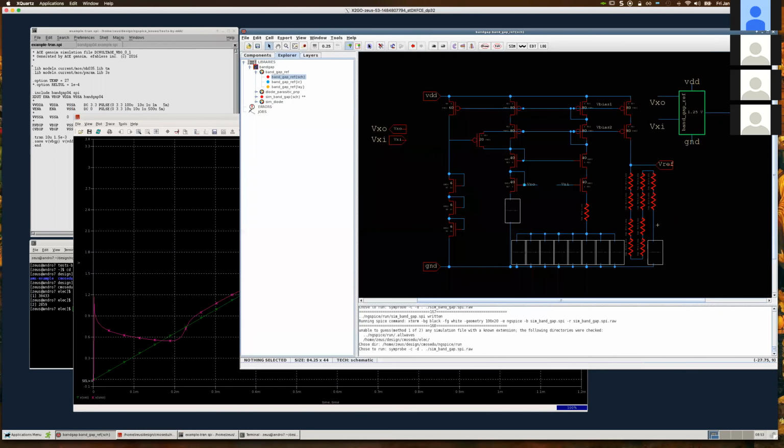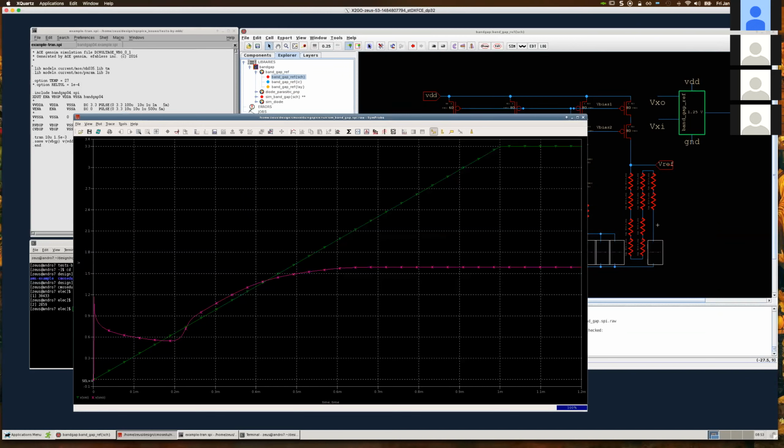If I'm sweeping one of them in a linear way, the circuit responds to that sweep of voltage here, and the other node, which in a real scenario is connected to it, you'd be able to see the response. There is a crossover, then there are multiple operating points, and that is very sensitive to temperature.